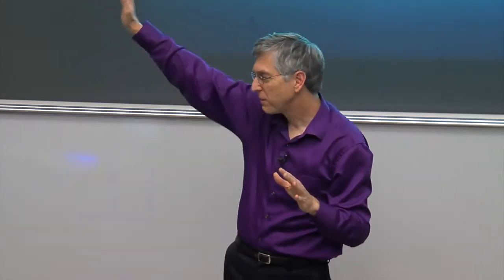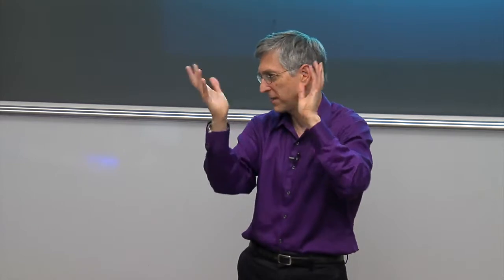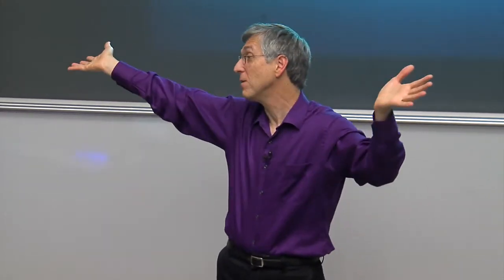So I do spectral harmonic balance things. I just do time domain in Verilog. It's very fast. And then I do the Fourier transform to do the harmonic stuff, and I look at whether I'm getting the tones that I want. There's no problem in doing that. But I think for digital simulation, modulo pulling out carrier effects, because I think we're going to have to do that, we're probably in an event-driven situation.